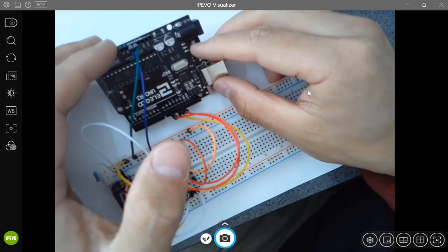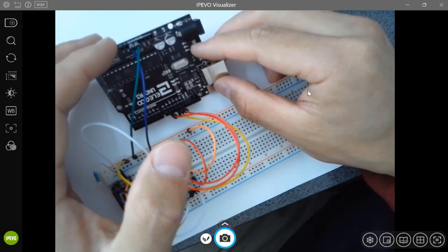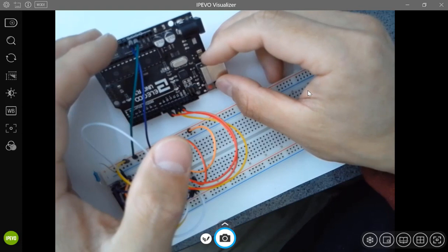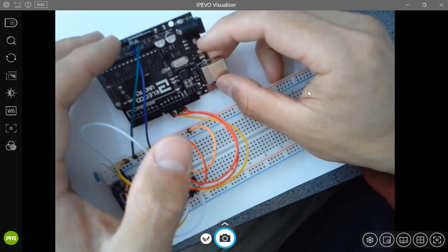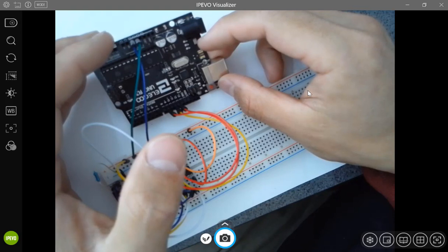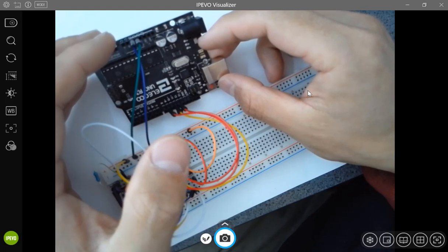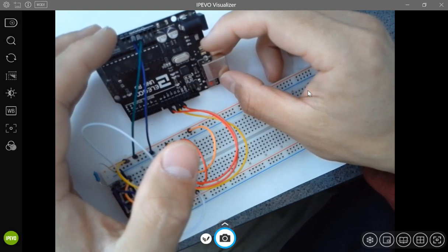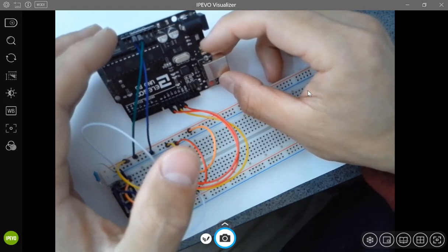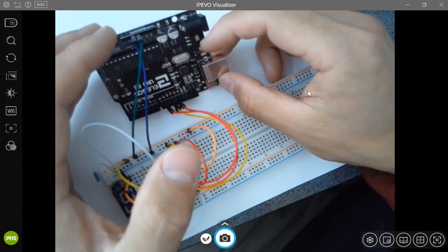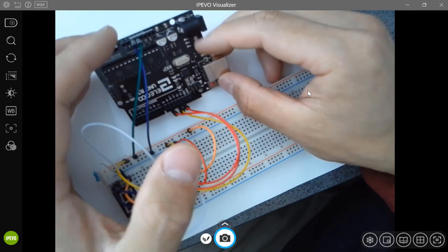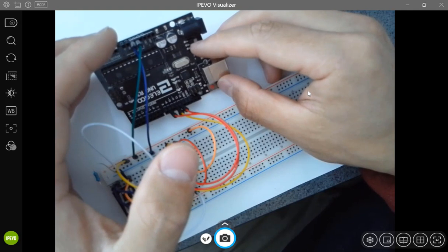Come on, it's a 5 volts regulator. I provide 7 volts, you are expecting 5 volts, right? What about 8 volts input? It's still 5 volts. It accepts a range, like 7 to 12. Whatever the input voltage is, it's going to give you 5 volts. That's how it works, right? That's the point of using this device. It's not really expensive and works really well.